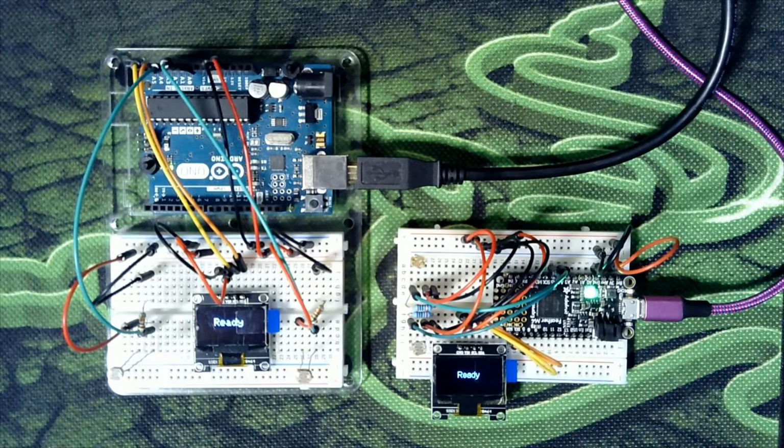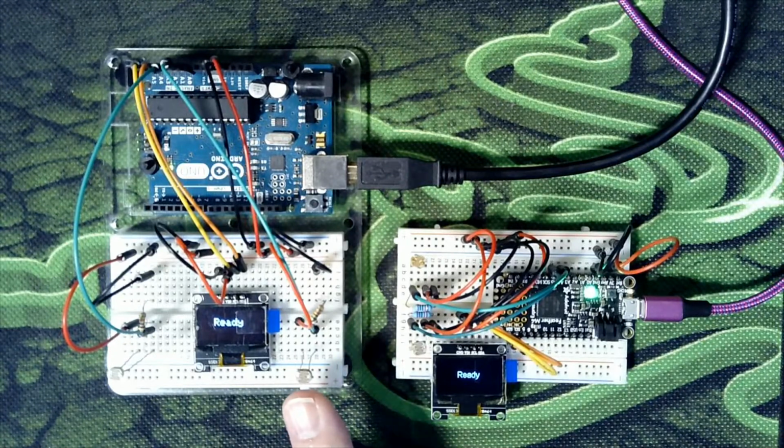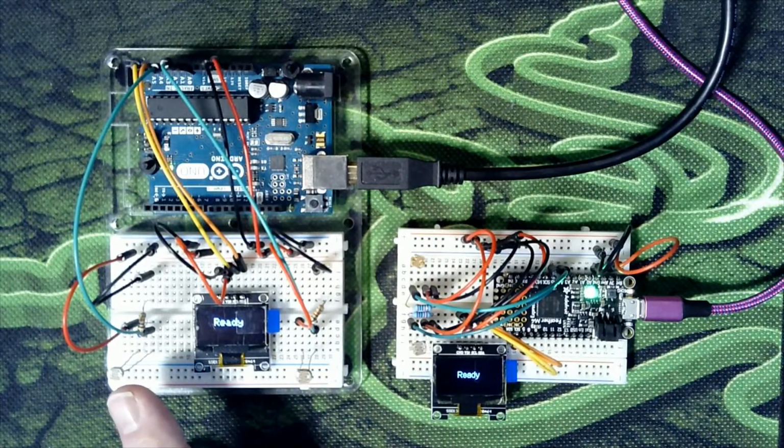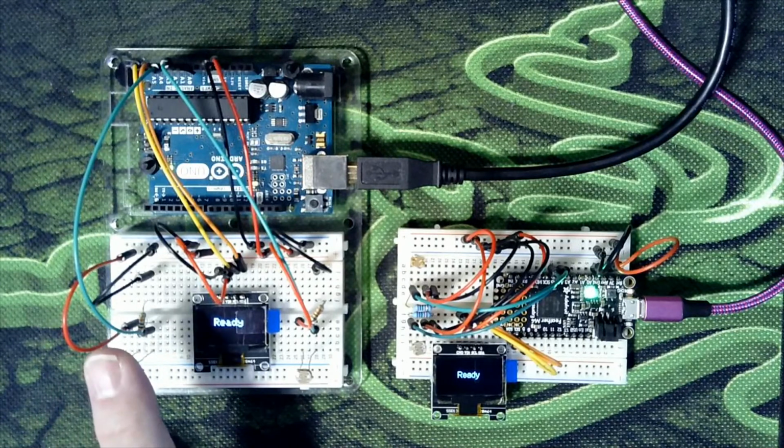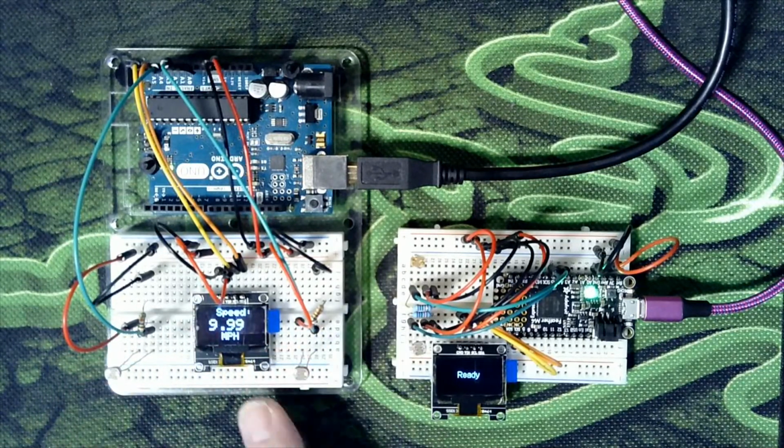We have a small display here so it can display out to the people that are watching. You can find out the scale operating speed of your trains by running past a couple of LDRs, those sensors right down here. These are light dependent resistors, and we've used them before, early on in this setup as well. Basically, one gets blocked, the train comes by and hits the other one, and with the amount of time I took there, it gave me a scale speed of 9.99 miles per hour. This is how it actually works.